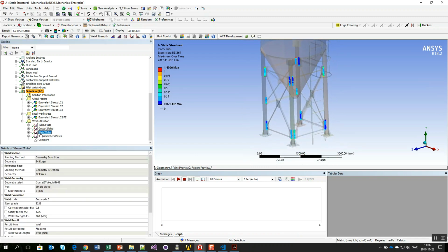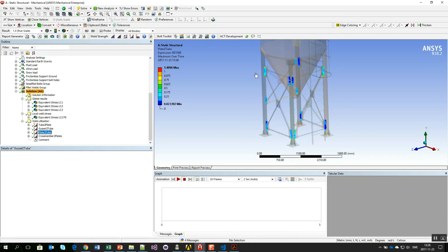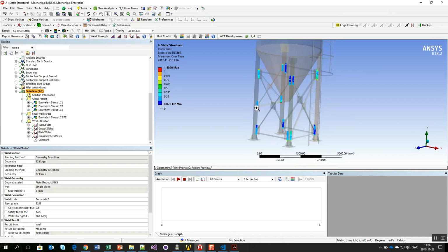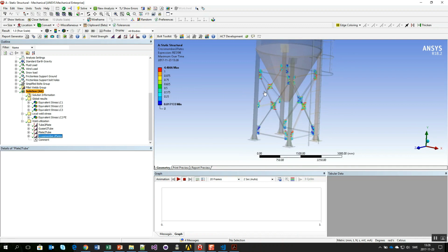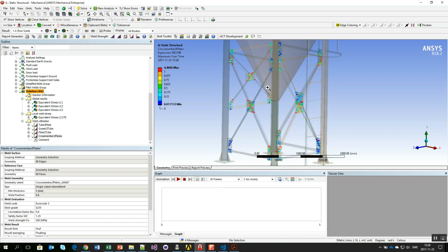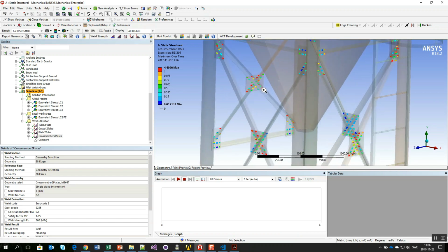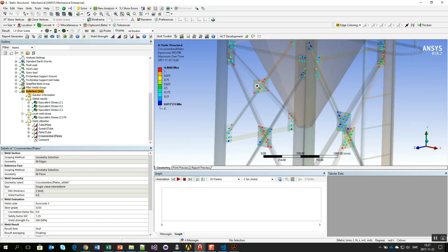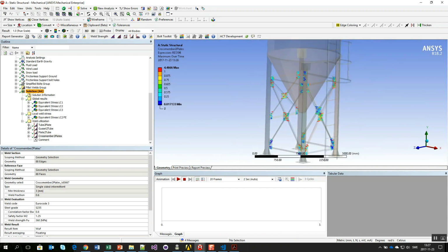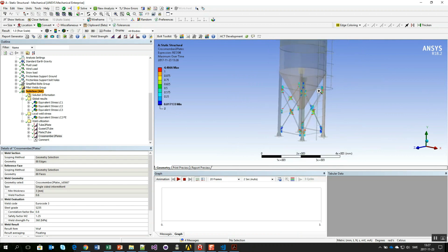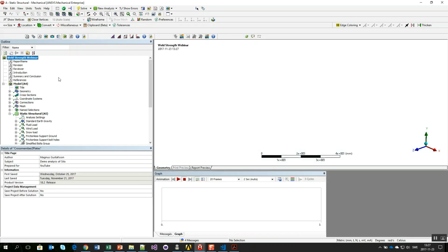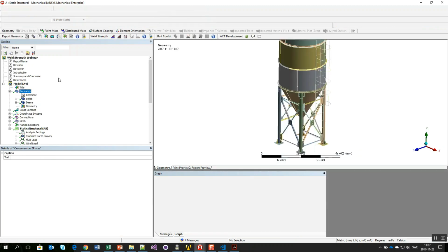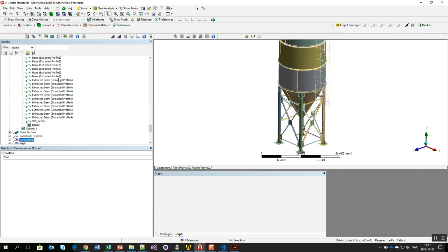So these are okay. Here we see some local hotspots are a bit above 1. This cross member welds with intermittent wasn't a good choice, so here I need to do an update to go to a continuous weld, for instance. So when I'm done here evaluating, I can simply now do the hard copy to get a report of this analysis.